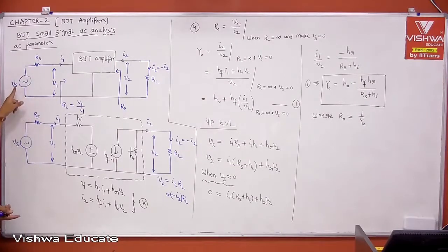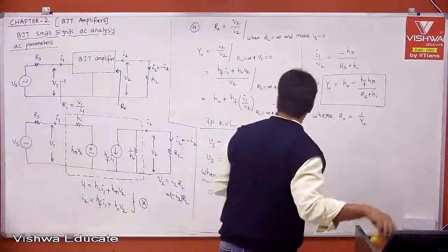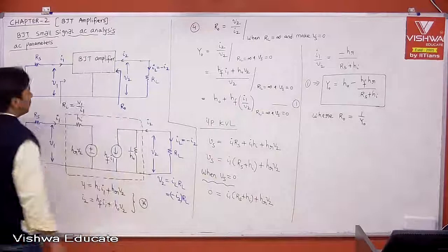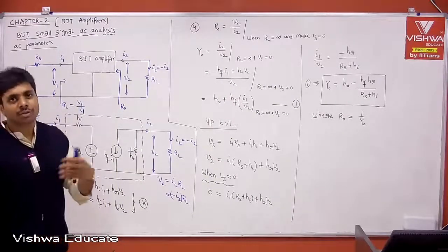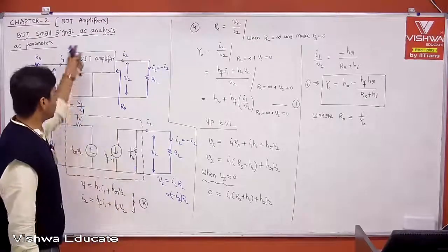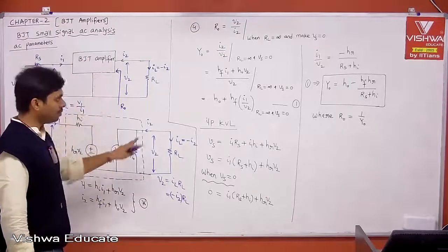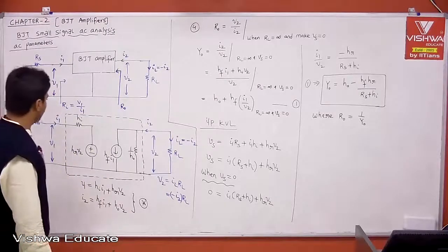But don't say that Vs is replaced with a practical current source, Is and then Rs. No, for a practical current source, it should be Is with Rs in parallel to Is. Further, we should take a practical current source, and we will see that part also. But they are not very important. These are all very important if you want to go on with the different configurations. Then we'll come back. Ultimately, the BJT amplifier core parameters, whatever we have solved till now, are very important. Okay, done.